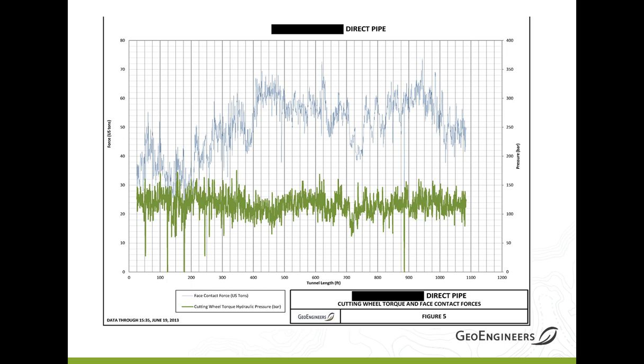So a couple slides here. Sorry, this is a different project. This is one we did in weathered bedrock, but you can see we're also going to look at horizontal location deviation with respect to whatever the standard or specification is. And I mentioned earlier the importance of doing an in-pipe survey to check that the data you're getting is good, and you can see here that we've had to correct the data by that survey process. So something to keep in mind.